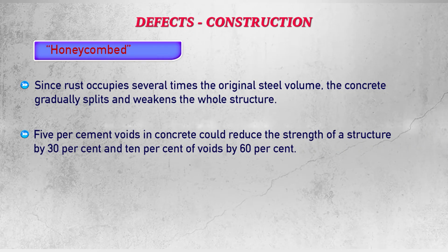5% voids in concrete could reduce the strength of a structure by 30% and 10% of voids by 60%. So it is so detrimental. If voids are there, then there will be huge reduction of the strength of the structure.